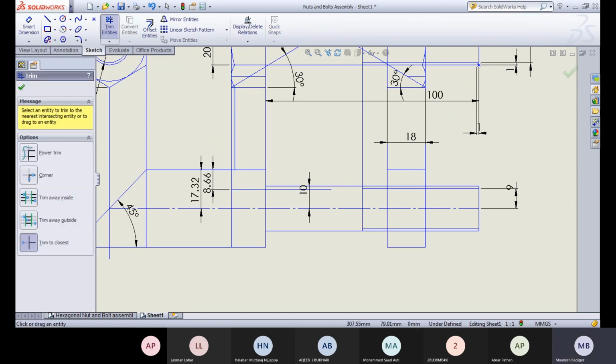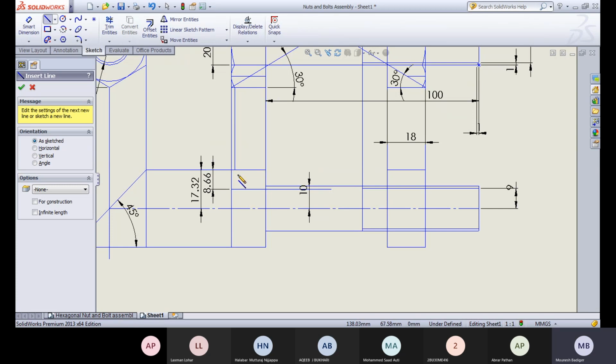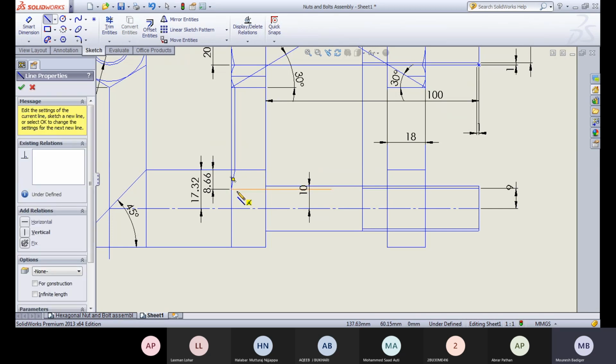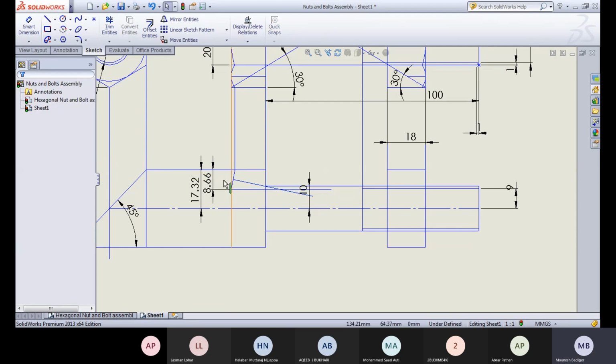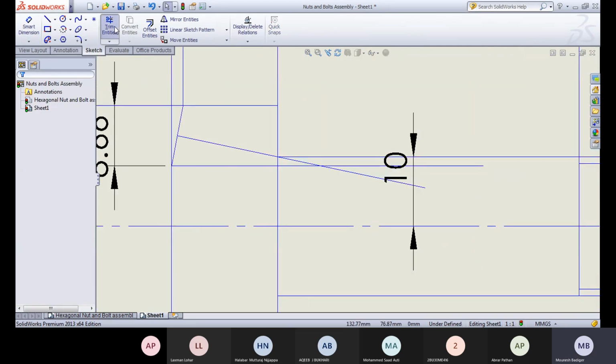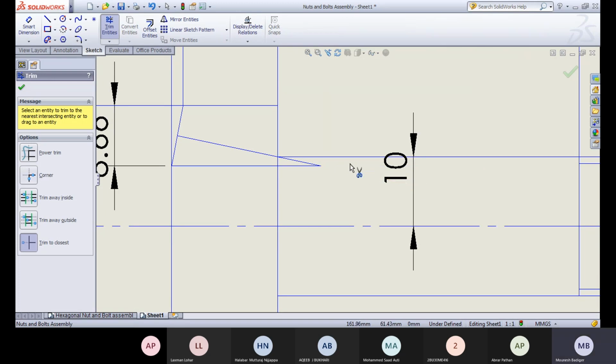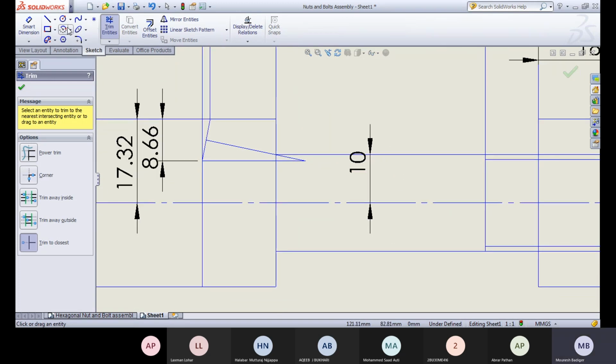In this point you just extend the line. Okay, let's remove the additional line. Just join these 2 points, then draw a perpendicular line to this. Okay, you can see the perpendicular symbol there that indicates that the line is perfectly perpendicular. You can just zoom in. We will get the center point for that.